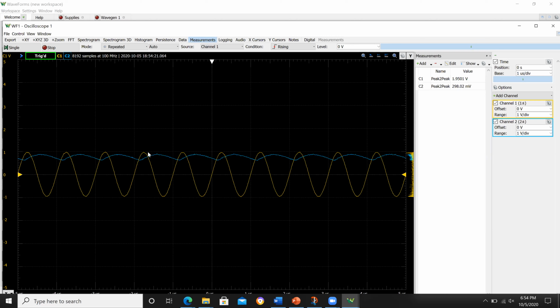What's going on here? Well, here's what happened. Your op amp, as I'm sure you're learning about in lecture, has something called a fixed gain bandwidth product. So what that means is that it is only capable of providing, for a fixed feedback network, a finite amount of gain within a finite amount of frequency.